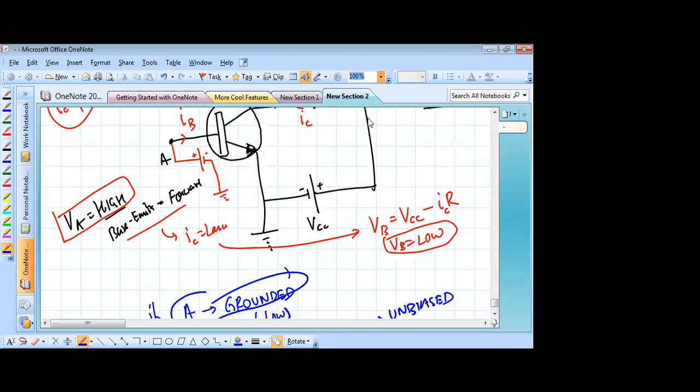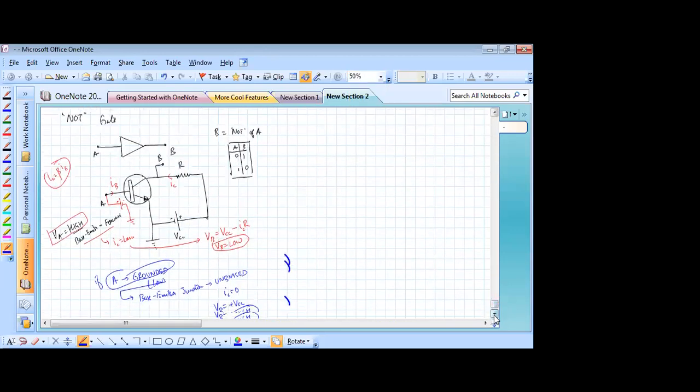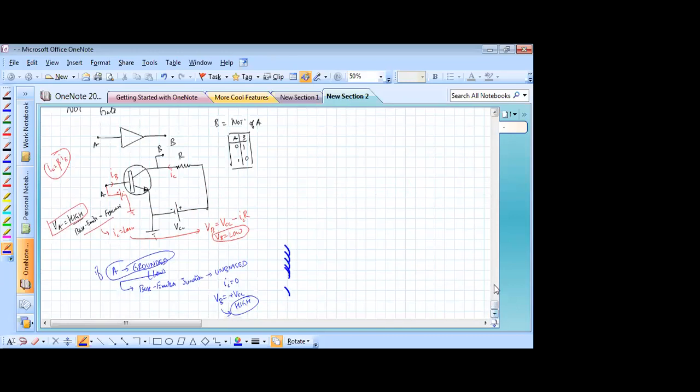So just leaving you for a moment with the circuit diagram. This is how we implement the three basic gates: the AND gate, the OR gate, and the NOT gate. The NOT gate using a transistor, the AND and OR gates using a combination of two diodes with other things. And all other logic gates which are more complicated, like the XOR or all these other ones, are just combinations of these.